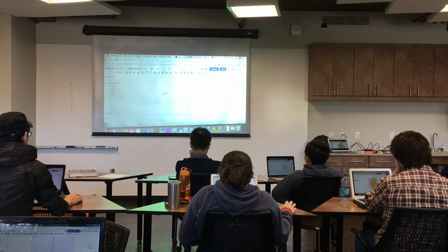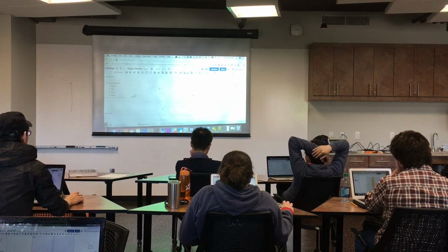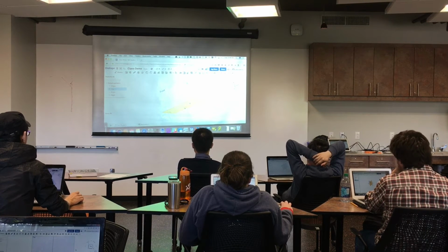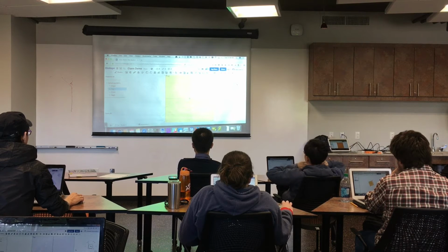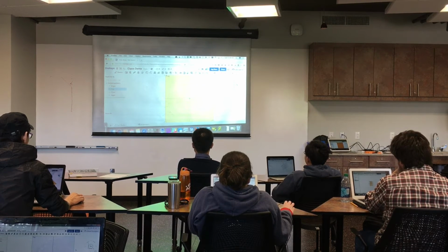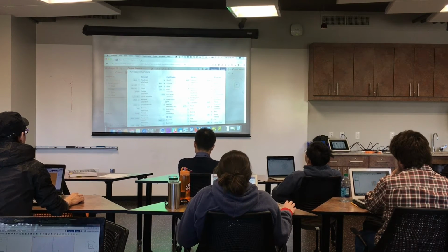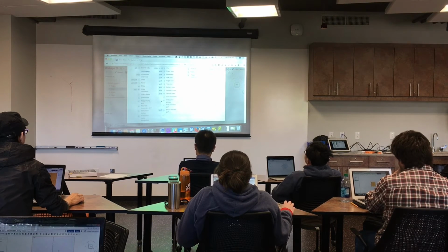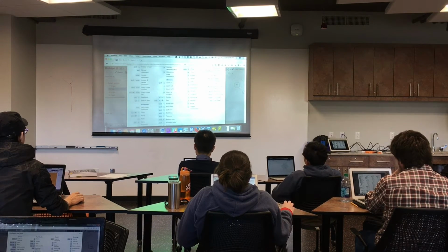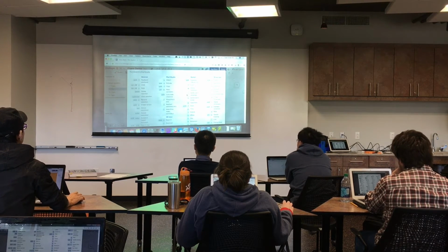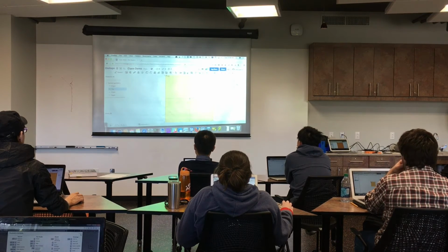And then you've got these planes. Oh, and to pan, you hold the middle mouse button. So hold your scroll wheel, and you can drag around like this. It's also nice if you have a plane selected, or if you're working in a sketch, you can hit N, and it gives you a normal view. If you get lost, you hit the question mark, and it brings up all these keyboard shortcuts, which if you use this much, you'll get used to them very quickly because they save you a ton of time. But I'm going to try not to use them since you can't see what I'm pressing on the keyboard. If I do, yell at me.